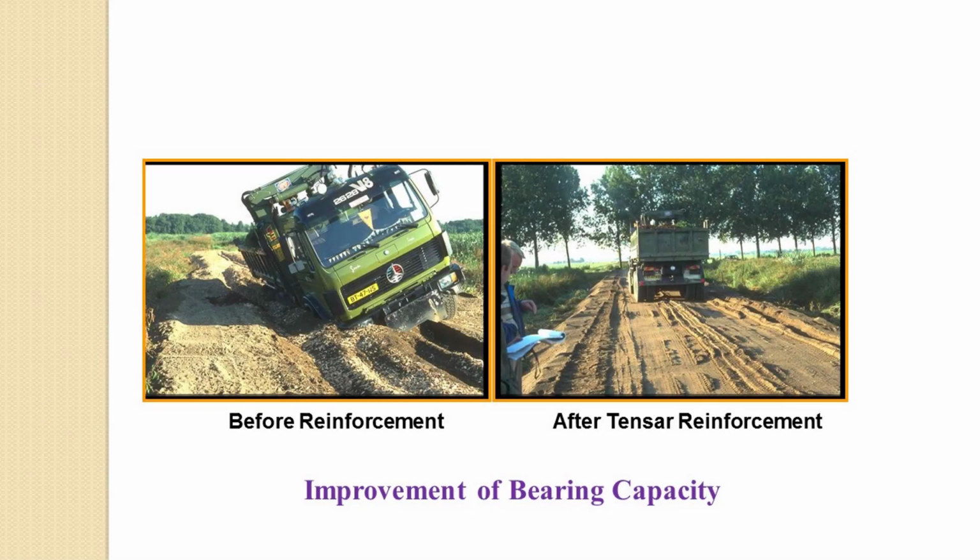Okay? But that is an unpaved road without reinforcement. This is what happened. Poor bearing capacity, this is what will happen. But if you have the same thing and you have used a geosynthetic, then probably it will be able to. There will be small rutting on this unpaved road, but still the traffic is able to move freely without getting bogged down.